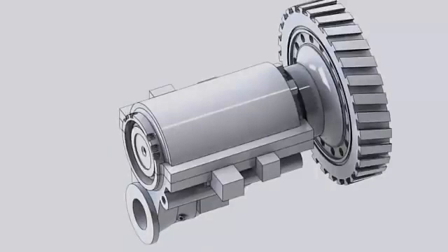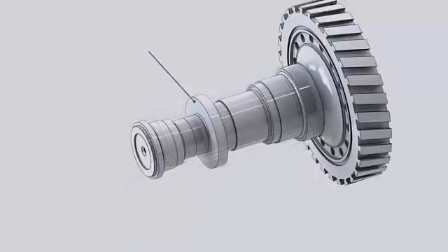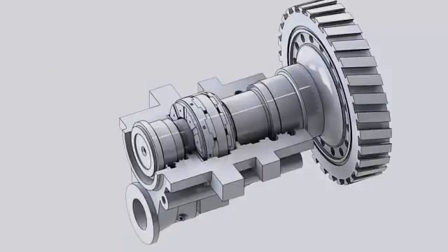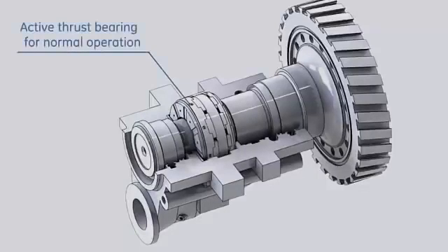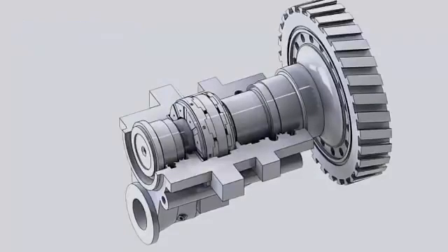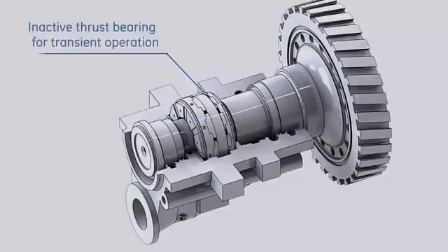The thrust-bearing major components are the thrust runner, which is integrated in the compressor rotor forward stub shaft, and 2 thrust bearings. During the normal operation of the gas turbine, the sum of axial forces induced by the airflow on the compressor stages and the hot gases flow through the turbine stages tend to move the rotor in the upstream direction, so that the active thrust bearing is located on the forward side of the thrust runner. During transient operation at startup and shutdown, the shaft tends to move in the downstream direction, where the inactive or unloaded thrust bearing is located.